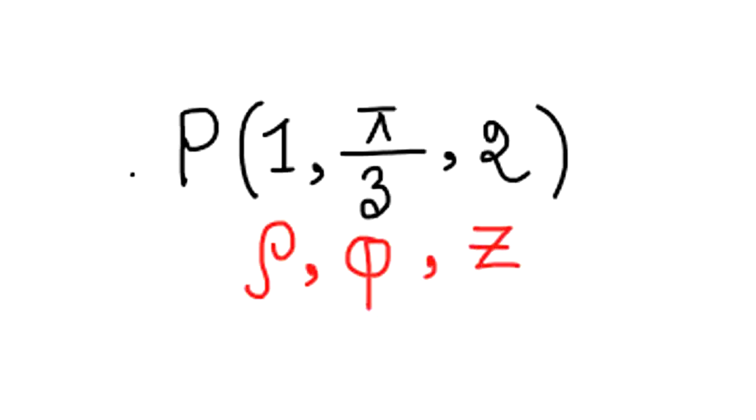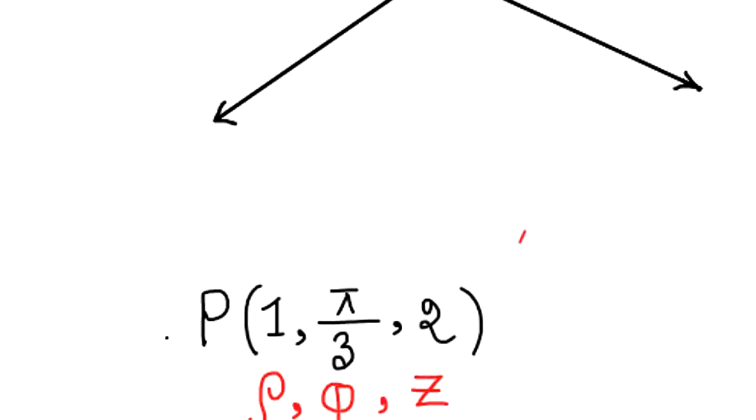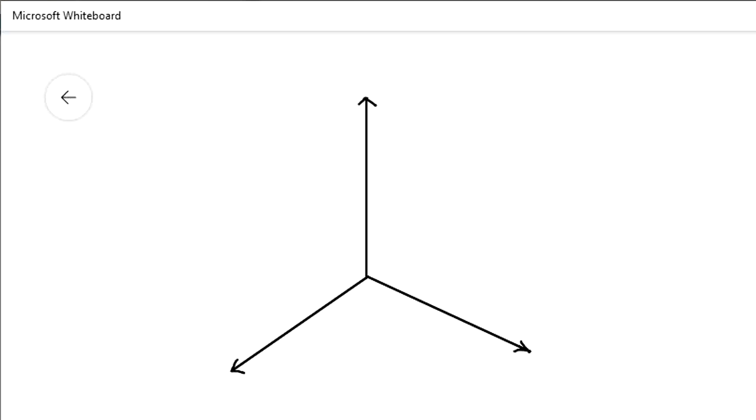So let's place it in a three-dimensional system. Let's take a three-dimensional system and place the axis. Of course, as we have named here, Z should be our central axis. So consequently, this axis will be X and this axis will be Y, right? So now what we will do is that first we will draw the projection of this point on the horizontal plane, which is on XY plane, and then we'll include the height.